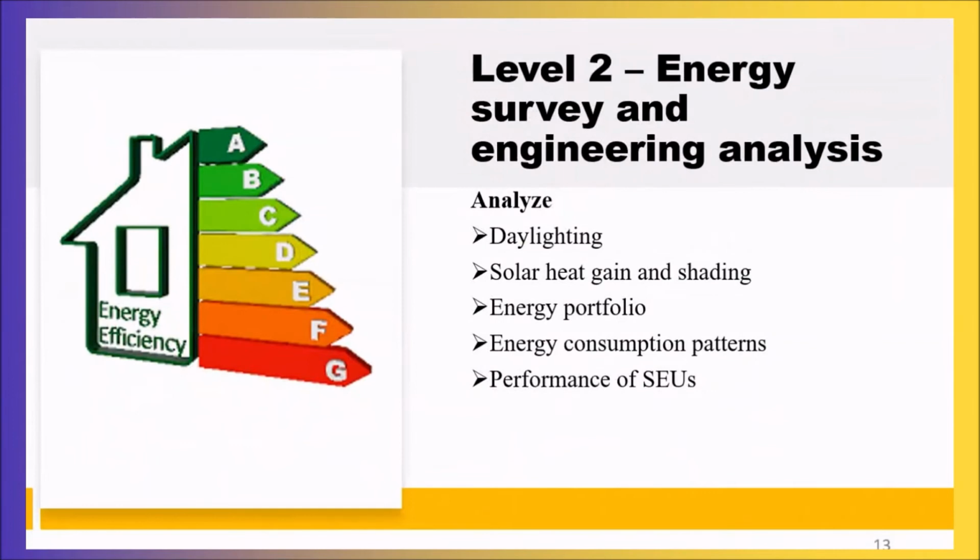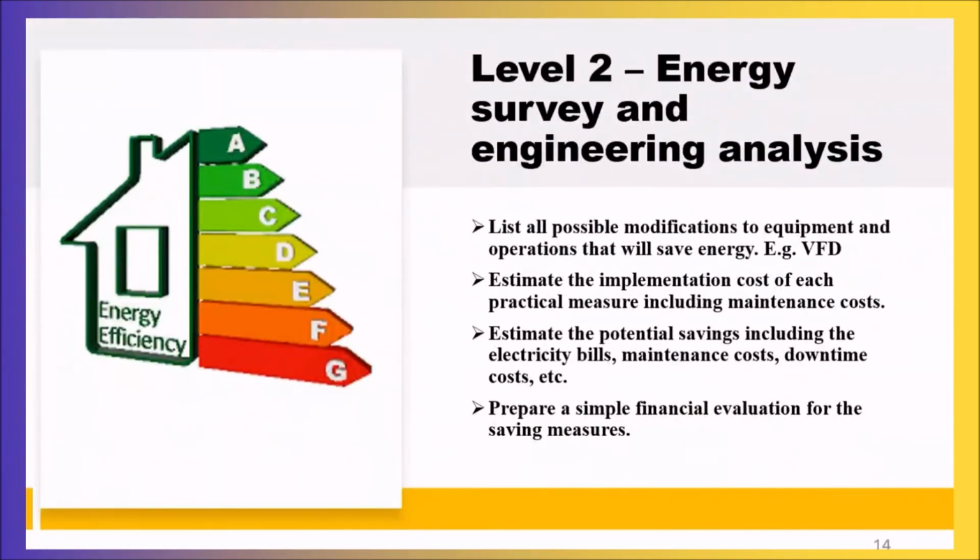You can analyze the daylighting, solar heat gains, and shading, energy portfolio, energy consumption patterns, and performance of the SEU. And finally, you can list all possible modifications to equipment and operations that will save energy, for example, variable speed drive or variable frequency drive for motor control.